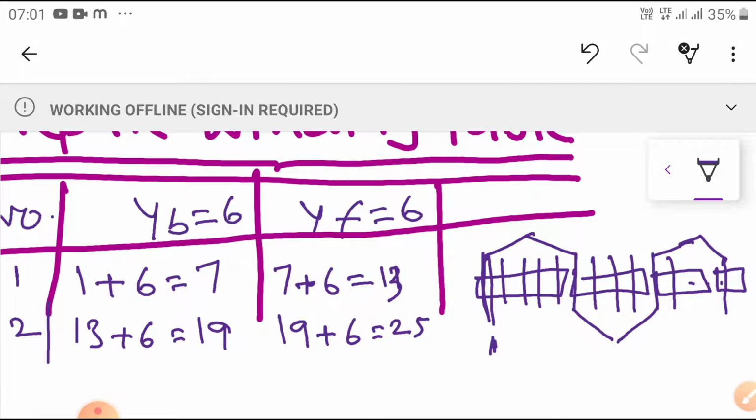So there is no chance. The 25th conductor is nothing but the first conductor, 24 minus 1, the first conductor as usual. But this first conductor in the first slot is already engaged with another coil. So there is no empty slot for this first conductor in the first slot.